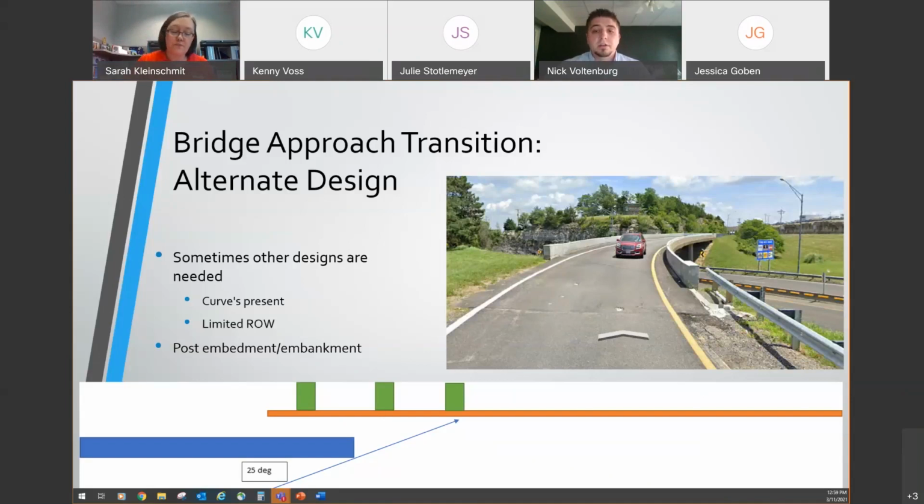The solution here utilized a standard end anchor that is tensioned and installed per Standard Plan 606-80. I do want to reiterate that this is only for a downstream roadway and cannot be implemented elsewhere. In this situation, the curb is located and protected behind the barrier, therefore it is unexposed and not a concern on the downstream end.